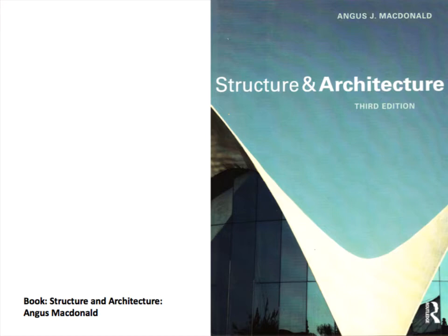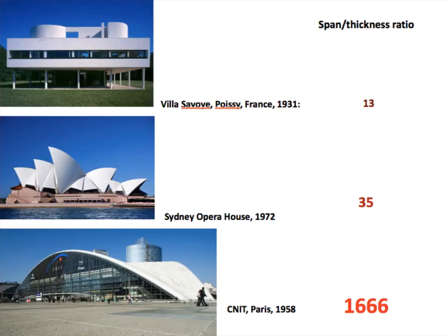This is a crucial difference because axial forces can be resisted with elements that are an order of magnitude smaller than those that are required to resist bending. And the type of internal force that occurs is entirely dependent on the overall form of the structure in relation to the pattern of load that it carries. The range of efficiencies that can occur is very large, as may be demonstrated by the following examples of very well-known buildings.